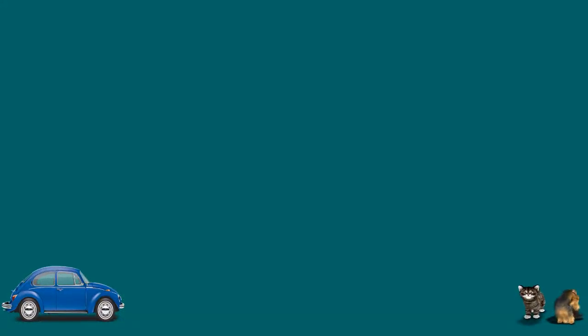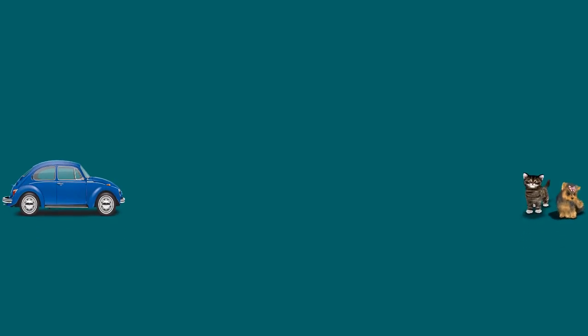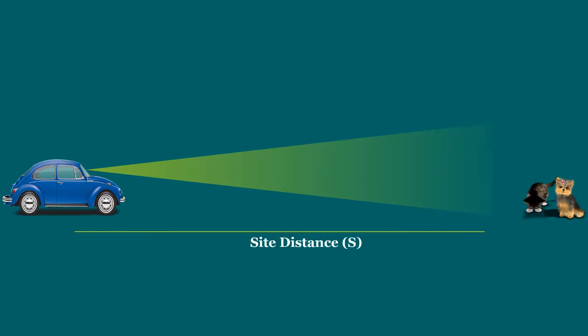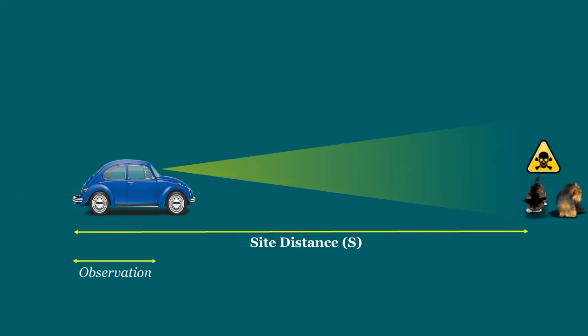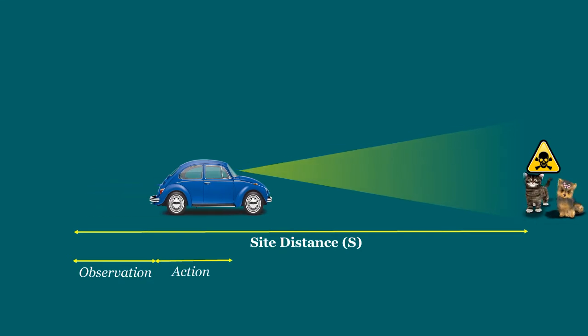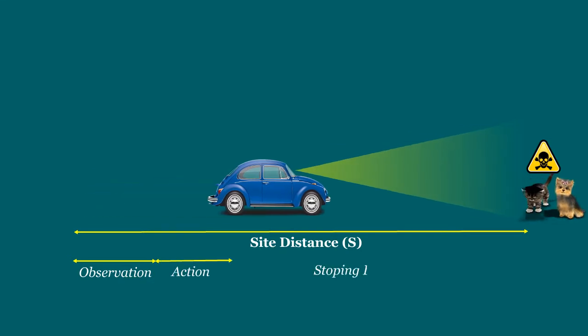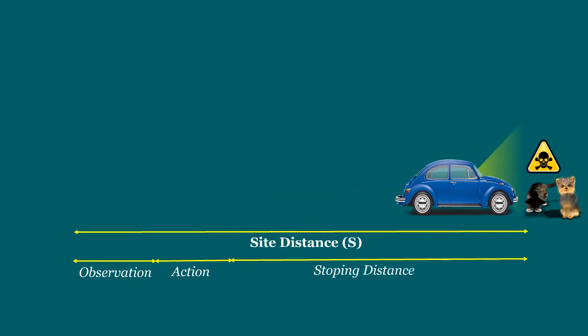In technical definition, the sight distance S is the length of roadway ahead visible to the driver, which is the stopping sight distance. This is calculated with due consideration of: 1. The time for the driver to perceive the hazard. 2. The time required to react. 3. The time to stop the vehicle after brakes are applied.